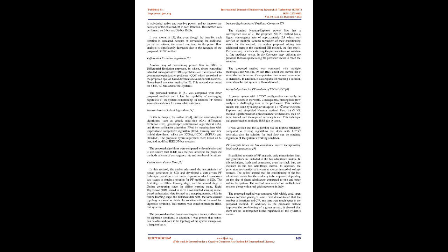In the offline learning stage, ridge regression, RR, is used to solve a constructed learning model based on historical data formed as a mapping matrix, while in the online computing stage, the historical data with the same current topology are used to obtain the solution without the need for algebraic iterations.